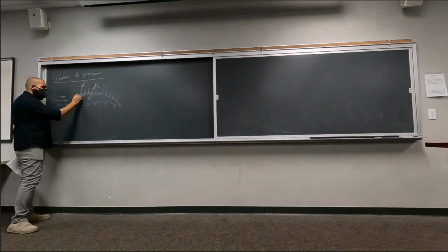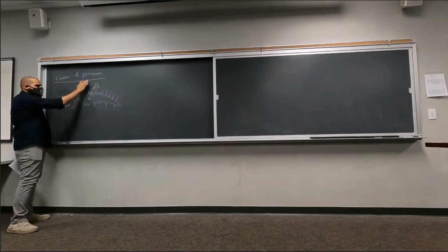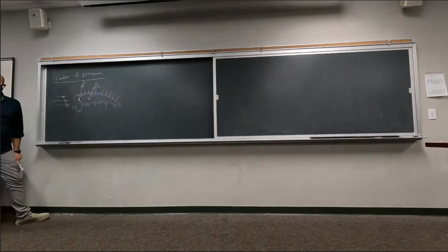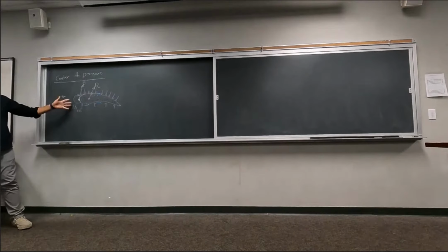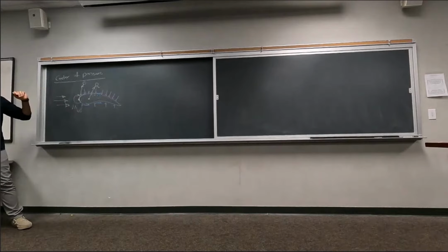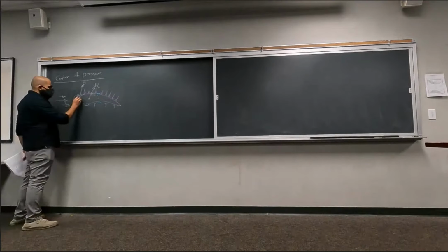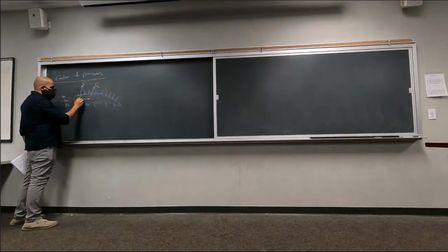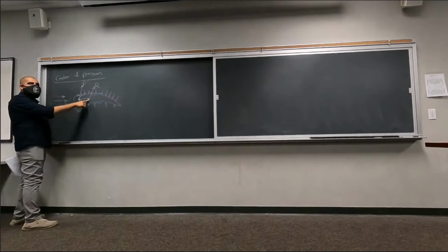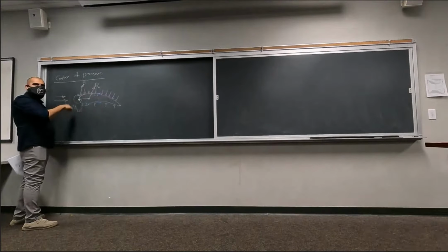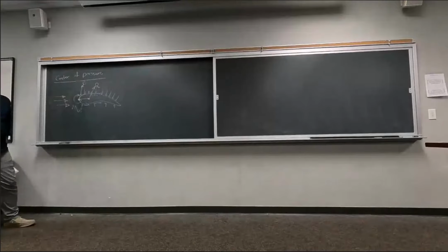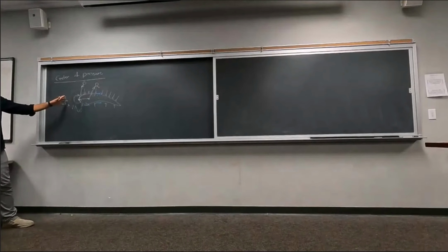Okay. So essentially what that means, if whatever we have at the leading edge is the combination of all the pressures and the shear stress that you're going to feel on this leading edge, the force we're going to have here has to exert the same moment as all of the pressures and the shears on the leading edge, only in the other direction, to cancel out that moment. Does that make sense?